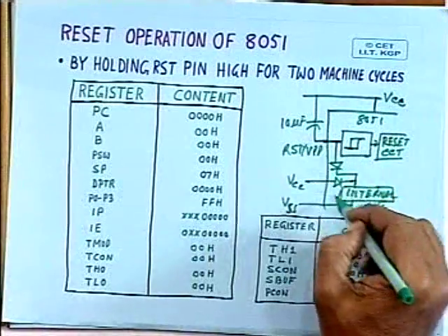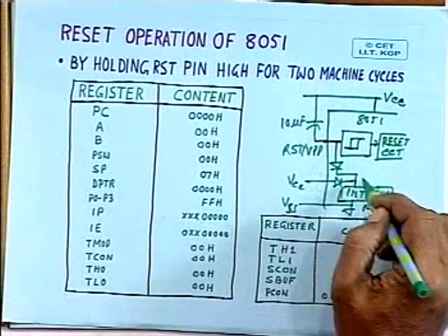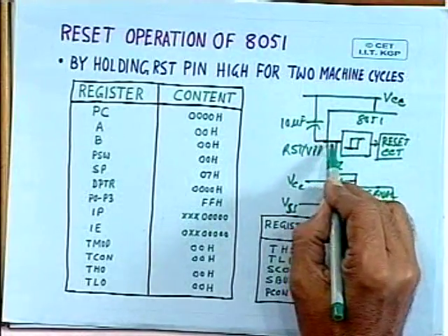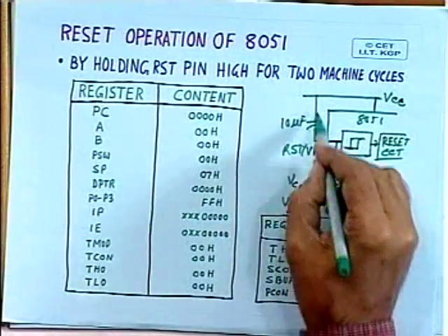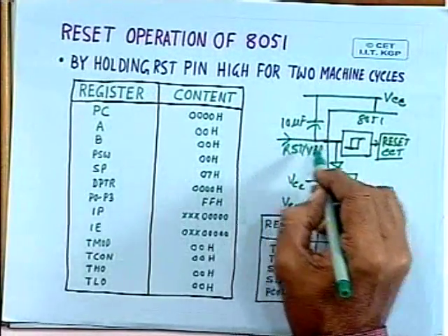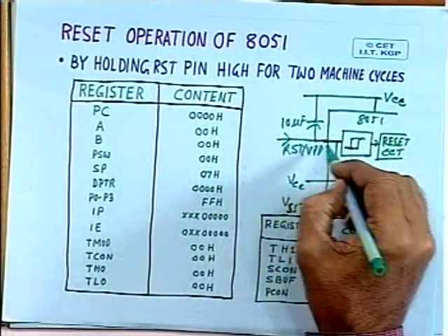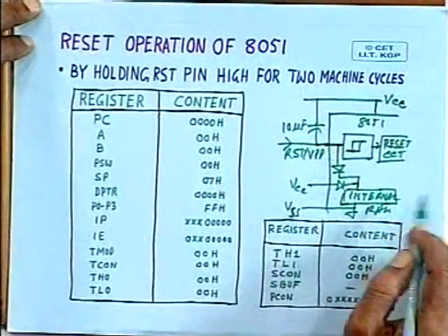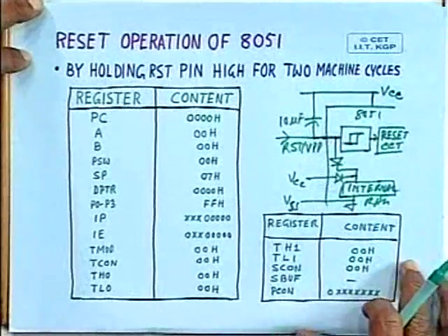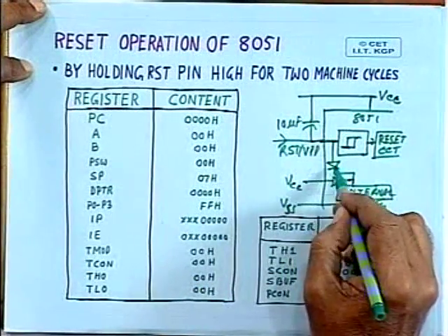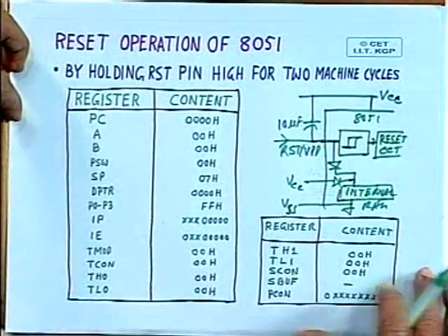So this is the internal circuitry of the reset part of the circuit. You can see not only does it do the resetting on power on, but you can connect an external supply voltage, maybe from a battery, which will retain internal RAM information as the power goes off. And as you can see, it is done with the help of these two diodes.